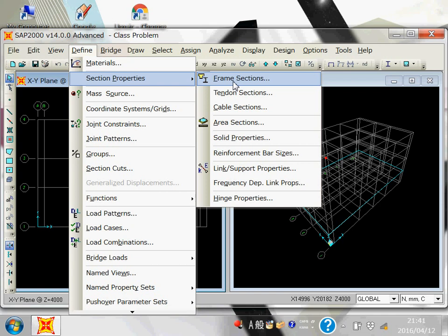If your reinforcement is always 3600 millimeter square, it means that it is the minimum reinforcement. You can also see the reinforcement ratio. So what you will do, you will reduce the column size like 450 by 450. Again you are getting rho minimum, it means you can further reduce the column size until you are getting some reinforcement which is higher than rho minimum.